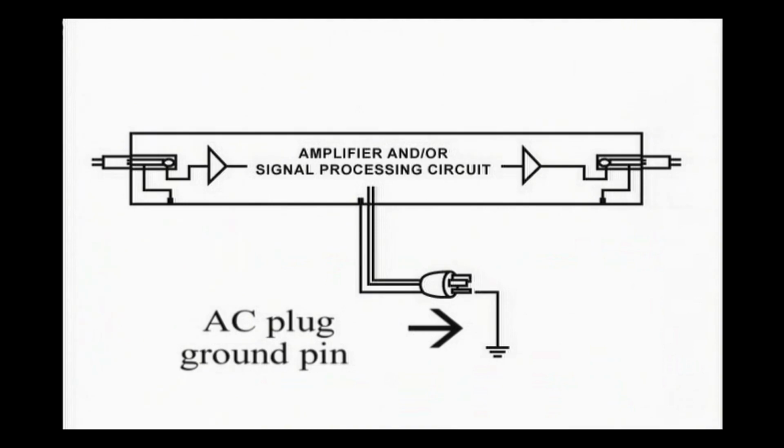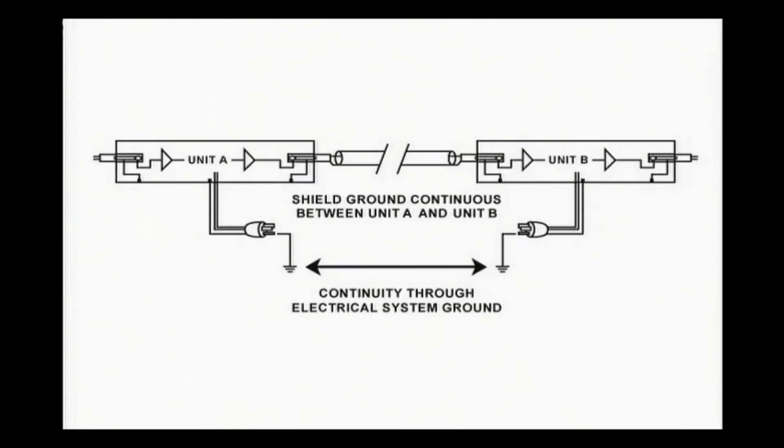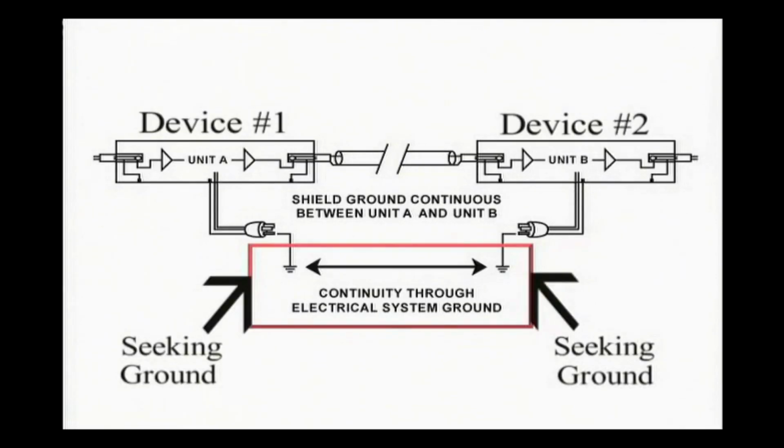In a sound system where there may be dozens of electrical devices, each with their own AC plug seeking ground, the very noise we want to eliminate often comes as a result of too many paths to ground. When there are too many paths to ground, loops can be created within the grounding paths, which act like antennas. These loops pick up the surrounding electromagnetic field, and rather than draining it off directly, recirculate it through the system to be amplified along with everything else we're amplifying.